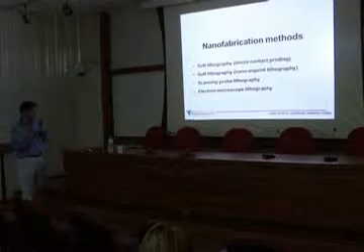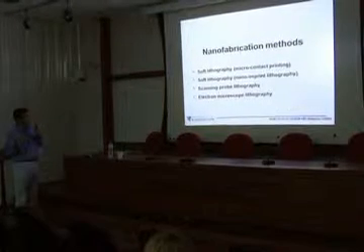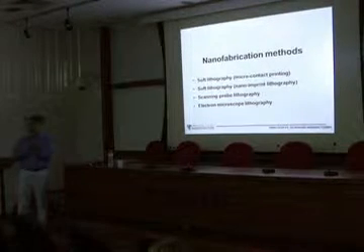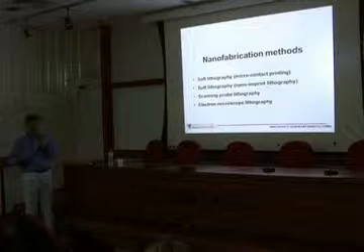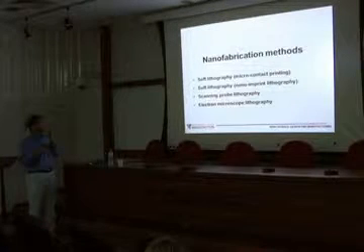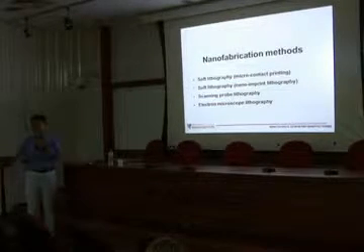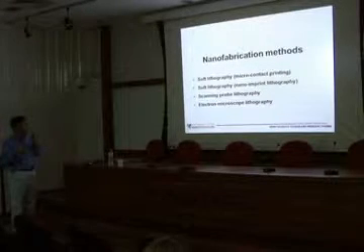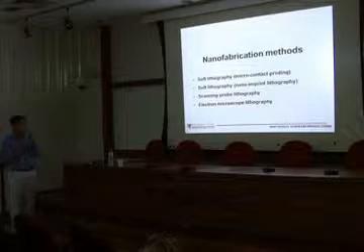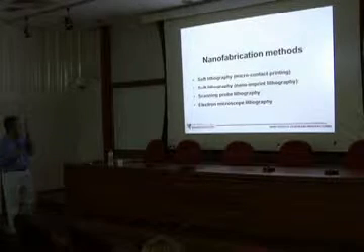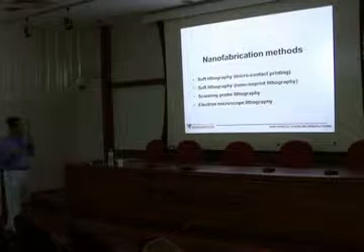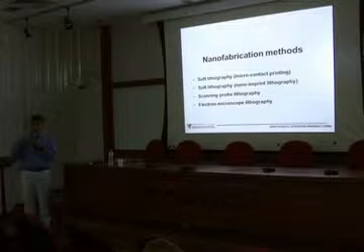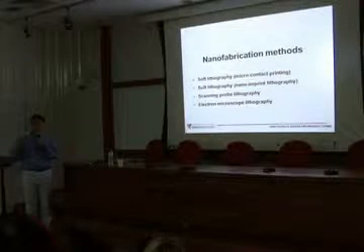One of the cheapest methods is micro contact printing. Even with a few hundred dollars, I can do micro contact printing at my home. And nano imprint lithography is a more improved form of micro contact printing. Scanning probe lithography is a lithography tool that uses a very small, tiny needle to make the structure.